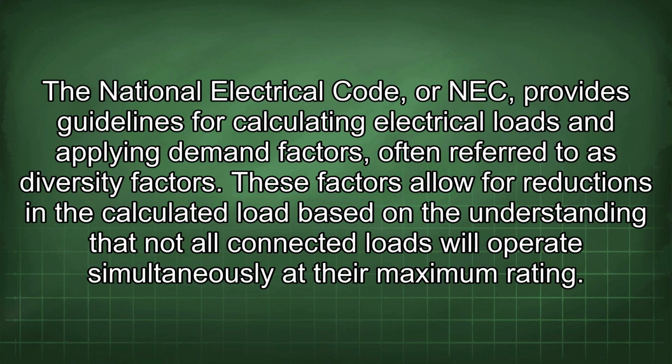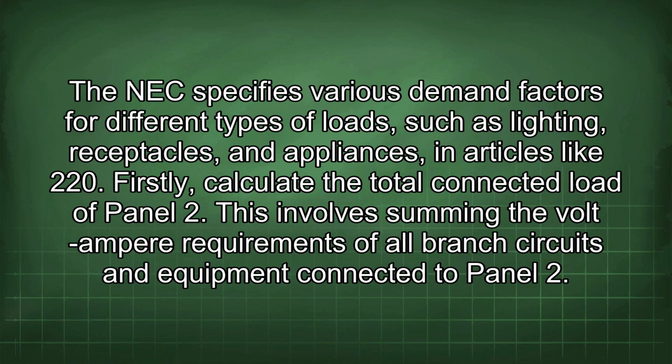The National Electrical Code, or NEC, provides guidelines for calculating electrical loads and applying demand factors, often referred to as diversity factors. These factors allow for reductions in the calculated load based on the understanding that not all connected loads will operate simultaneously at the maximum rating. The NEC specifies various demand factors for different types of loads, such as lighting, receptacles, and appliances, in articles like 220.